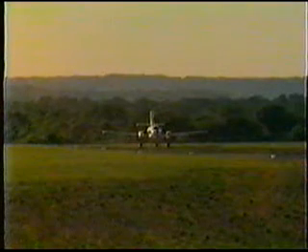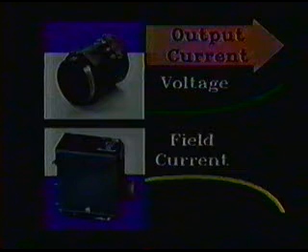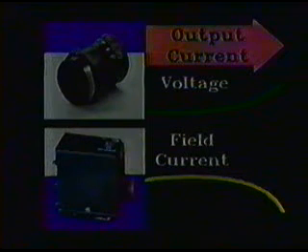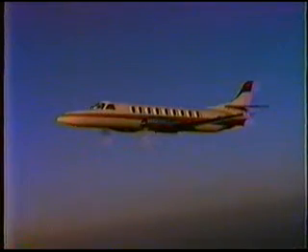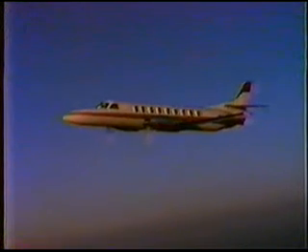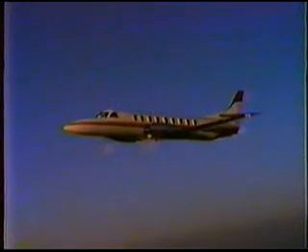Now the pilot has completed his pre-flight activities and begins to taxi for takeoff. As he advances the speed levers, the engine RPM increases. Since the generators are now being rotated faster, they would produce more electrical power. Again, the generator control panel senses this condition and decreases the strength of the generator field to maintain the proper output voltage and load sharing. During flight, as the electrical loads are increased and decreased, the generator control panels must increase and decrease the output of each generator as well.